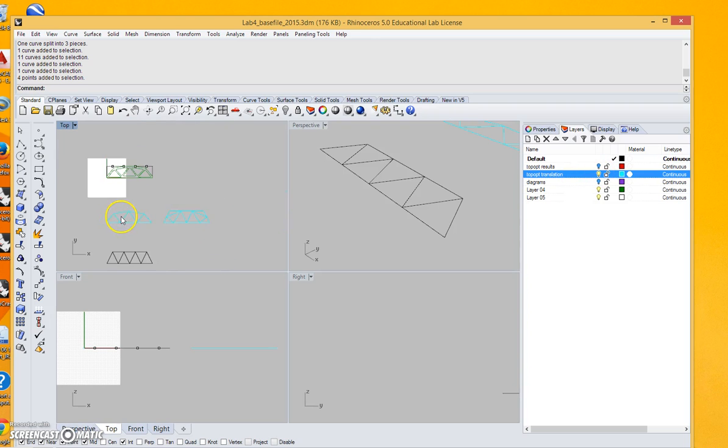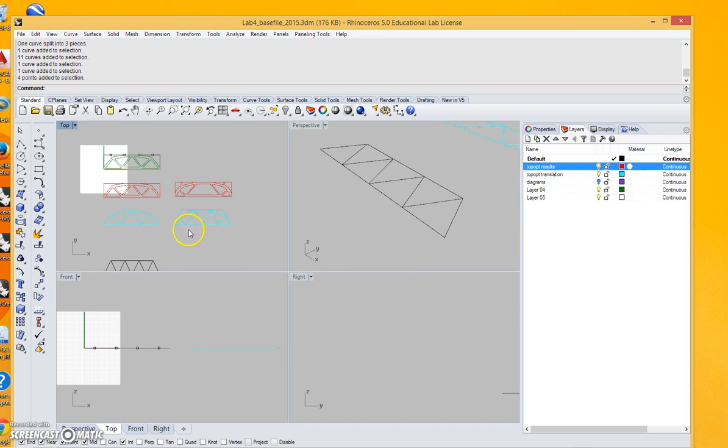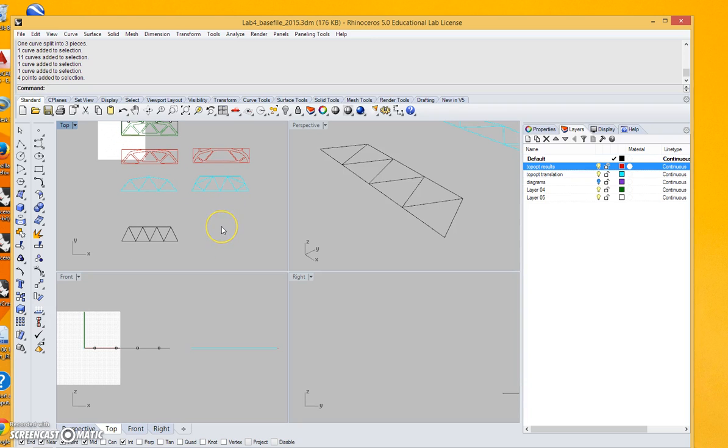And you can see that I've already then tried to trace lines over the baked result, both for this point load version and then also another one where I used the distributed points and got a slightly different output for that. So you can play around with the way that you translate this. There's some guesswork involved in exactly how you want to connect those members. And then the goal is to input 2 of these, the Warren truss and one of your translations, into Karamba and test to see what the ratio is between material used and deflection.